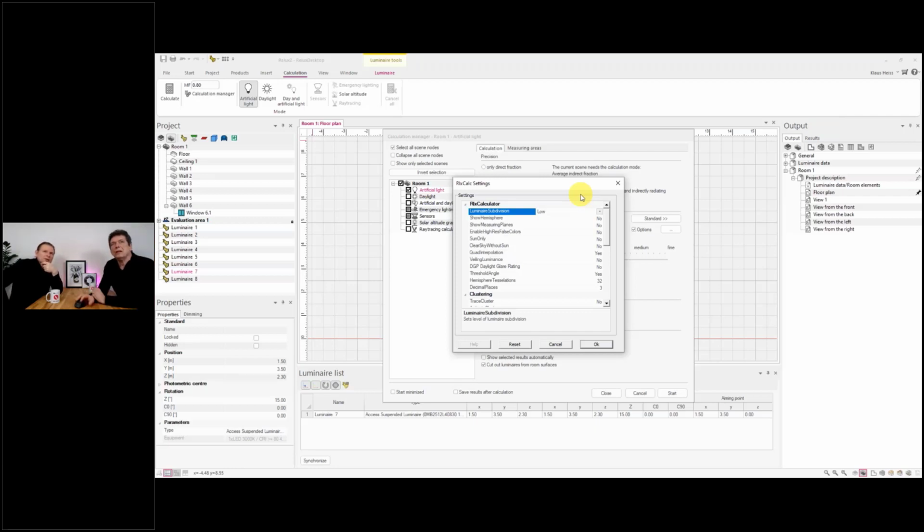There's something special here. You can set how much it should be, and the higher you set this value, the more calculation time we also need for this. But you have a lot of daylight options, clustering options, and even some grid options. You cannot really mess up the calculation, and you can also not really cheat in the calculation so that you always get instantly 500 lux on everything you need. This is something more for the advanced users.